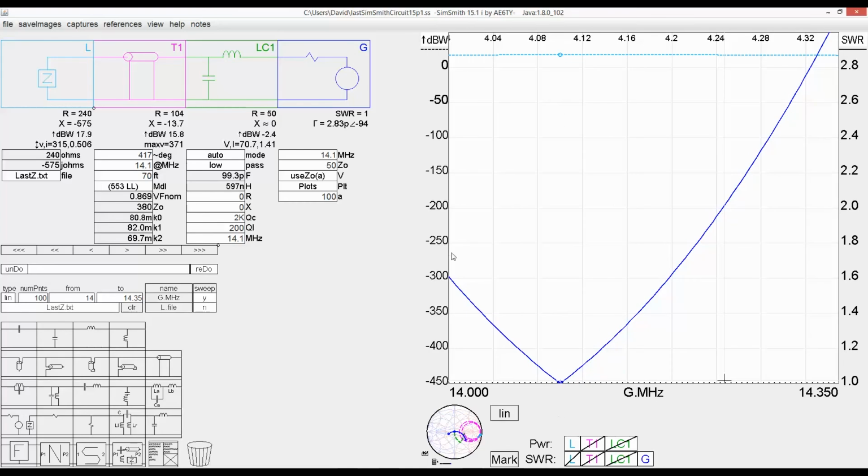Let's look at it in terms of power, dB watts. Change the scale over here. We've seen dBm, that's dB milliwatts. This is dB watts. So 20 dB watts is the equivalent of 100 watts. It's 10 to the second power. The formula, you multiply the exponent 2 by 10, that gives you your 20.